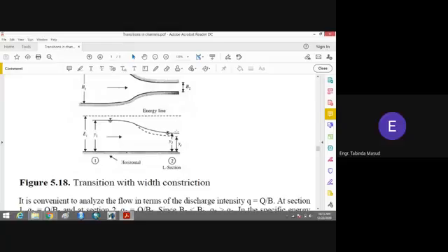The depth will change, but it will remain the critical depth for you. So what I mean to say is that the situation is the same. If you want to have a control section in the contracted section, if you want to have a critical situation in the contracted section, then you must provide the maximum contracted section which gives you the critical depth of the flow.